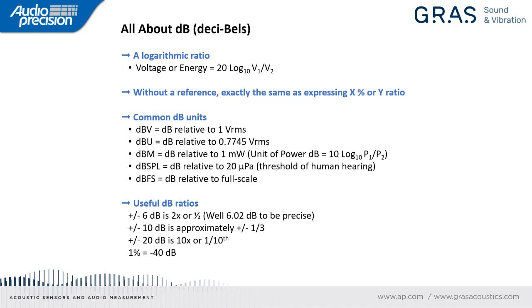Now, in most audio measurements, when people talk about dBm, it's really being misused because 600 ohm terminated analog interconnects are quite rare. So dBu was invented to represent the voltage that a dBm system would have into an open circuit.